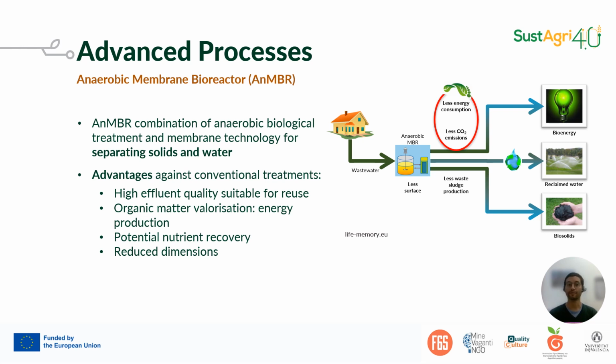The development of water treatment has allowed the implementation of advanced technologies. An example is the anaerobic membrane bioreactor. This treatment combines anaerobic biological processes with membrane technology, with all their advantages. These advantages are high quality of the effluent, suitable for reuse, energy production from organic matter, possibility of recovering nutrients, and more compact facilities.